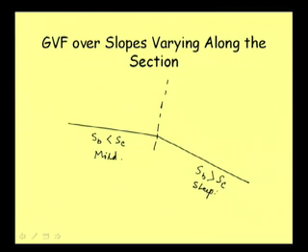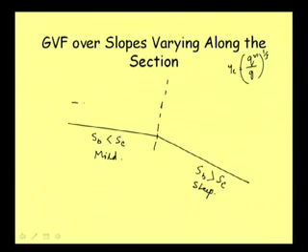So, mild slope is changing to steep slope. Okay. And then, so far as critical depth is concerned, again critical depth yc, if it is a rectangular channel, it is (q squared by g) to the power 1/3, whatever may be the channel, it is not basically depending on the type of slope on which it is occurring. So, we can draw the critical depth line at a section like that.